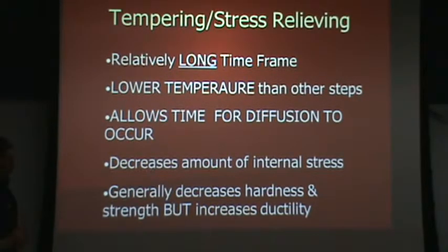Okay, so that was tempering. Talk about stress relieving as a separate operation from tempering. When you're making some parts, especially large, long components, and you go through the higher temperature heat treatment operations, you go through quenching, it's not uncommon that they will bend.